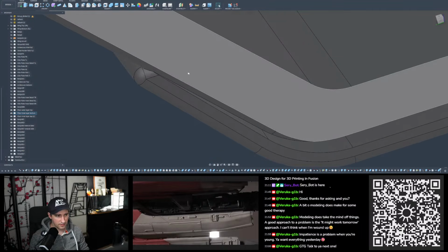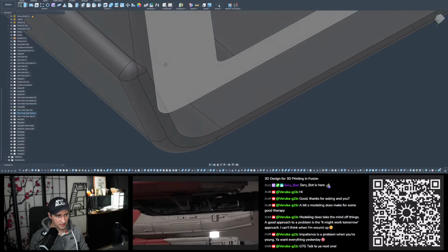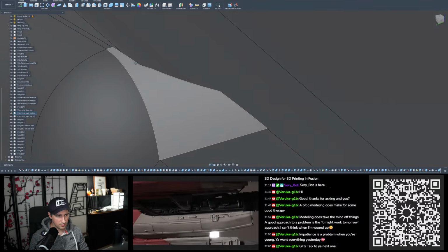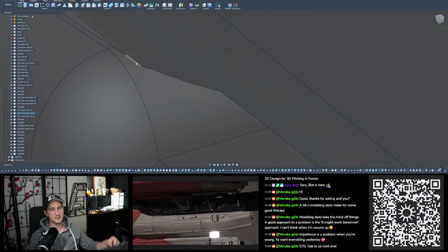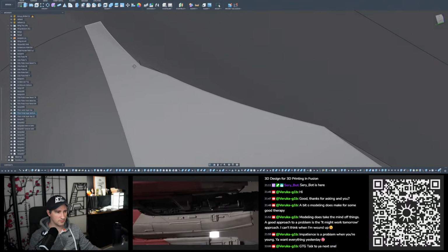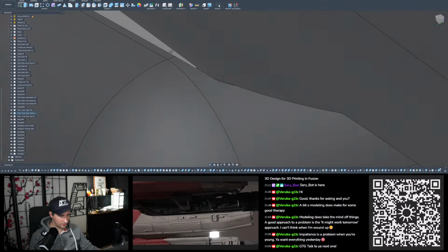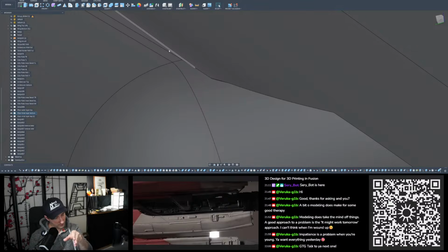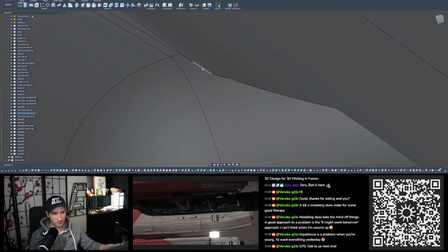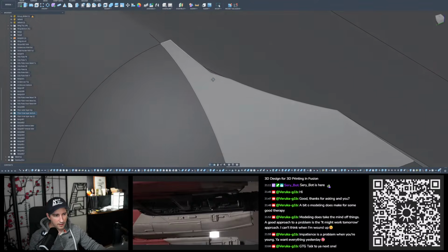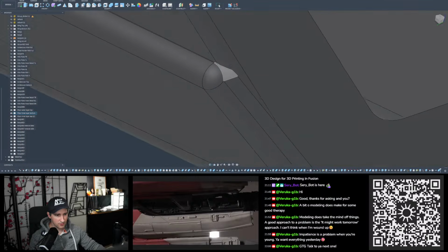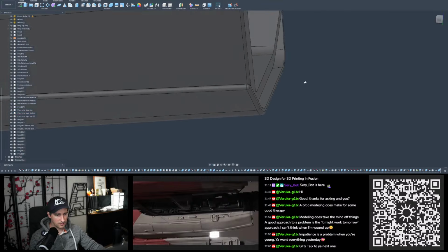because if there are cavities in the model, then when you 3D print, those will not be cured, so you will have forever uncured resin inside your model, and that's not cool. Especially if something breaks, just coincidentally at that part where the cavity is, and then that uncured resin can spill out and make a huge mess. So that's why it's important.